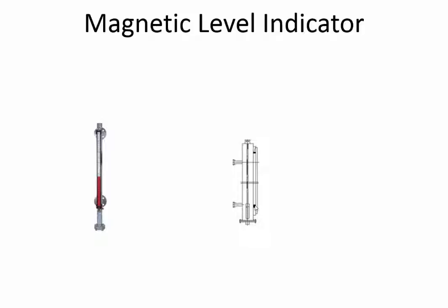This corresponds to these small little magnetic pieces which can flip 90 degrees, and as the float rises it causes these to flip over and indicate red, and as the float lowers, they flip over the other way and turn white. So the level in between the red and the white is the level in the fuel tank.